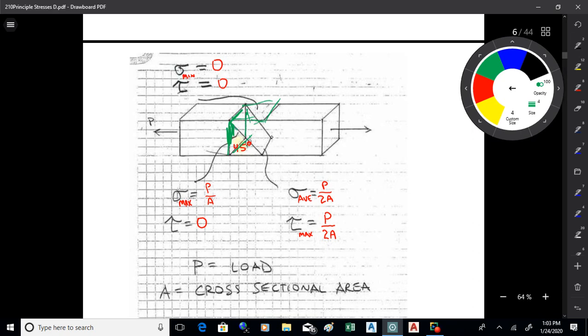And then we have a plane midway between the two where the maximum shear is, okay? And that kind of makes sense to me, that the maximum shear, the slipping, would be midway between the maximum polar push and the minimum polar push, okay? So halfway between those two at 45 degrees, you've got the tau max plane. Also on that plane, you have the average normal stress. So that's the relationship in uniaxial, and those hold for biaxial too, okay?